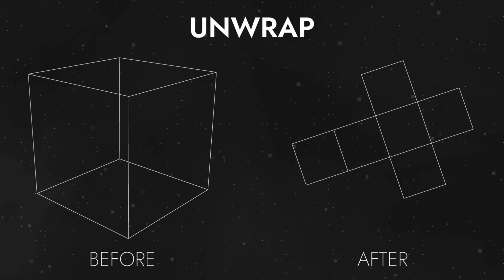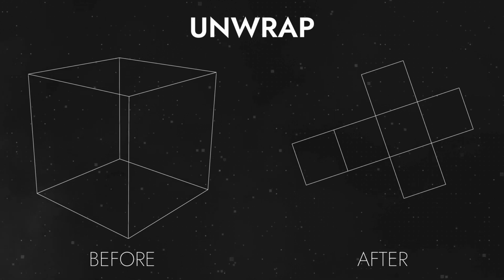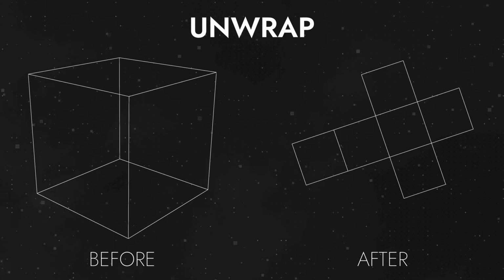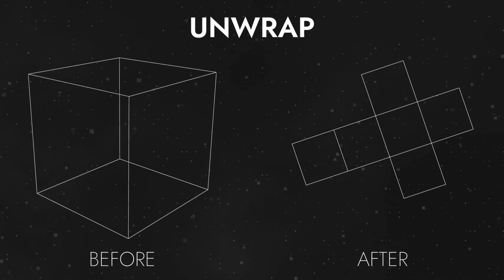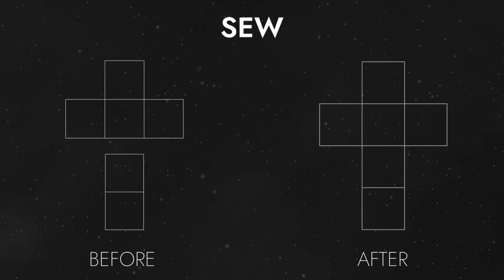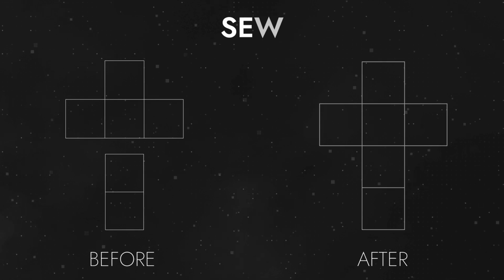Second tool is unwrap. After marking seams, you need to apply the unwrap command that will unwrap your model. Depending on the software, the command may differ, resulting in different outcomes, and there are also several settings you can adjust to get the best results. So, you can sew each created seam either on the model itself or in the UV editor.